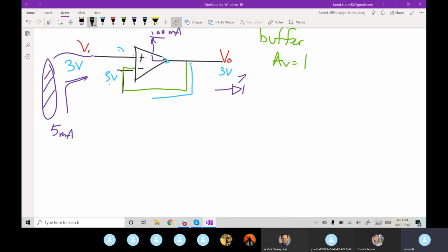It's if you have something that is of low current and you don't want to distort it, you want to make sure you keep that same voltage range because maybe that's super important to get the actual sensor readings, but you just need a little bit more current so that it's actually able to drive something. You would use a buffer. When do you use a MOSFET instead?